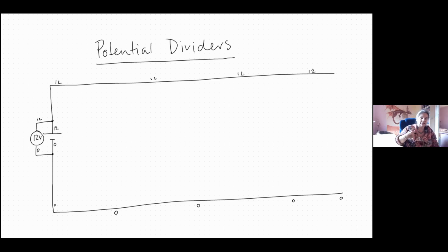Okay. Right, now, the voltmeter that is across my battery here has got 0 volts on one leg and 12 volts on the other leg. And voltmeters measure potential difference. Remember that the difference in potentials is the one minus the other. Okay, so 12 take away nothing is 12 volts. So guess what? That voltmeter reads 12 volts.